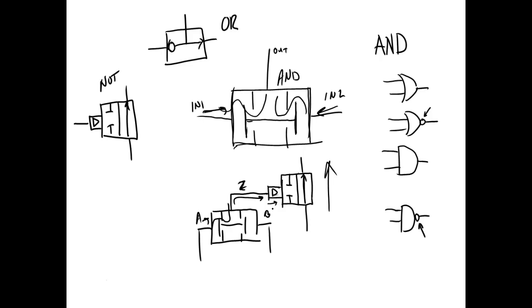In digital, and in PLCs, programmable logic controllers, we do logic. But we do logic with wiring relay contacts, or contacts that make a circuit, and we can wire them AND, we can wire them OR, we can wire them NOR, we can wire them NAND. Once you understand when all inputs are true and that kind of stuff, it makes it a little easier to understand logic. And you can understand why we need to do logic.